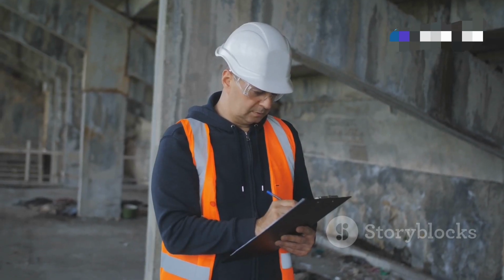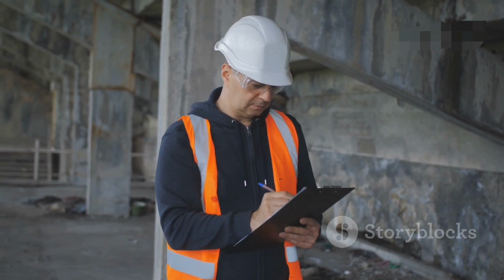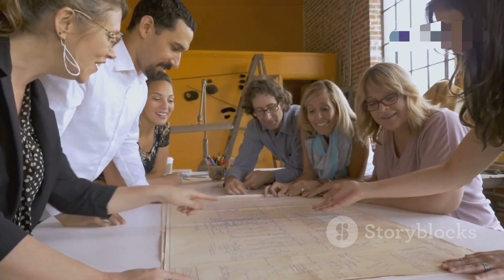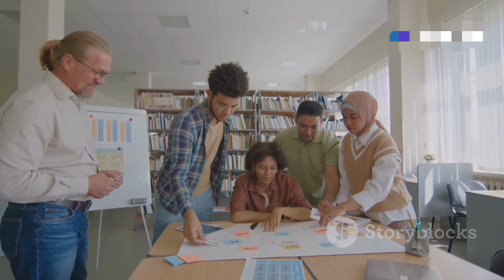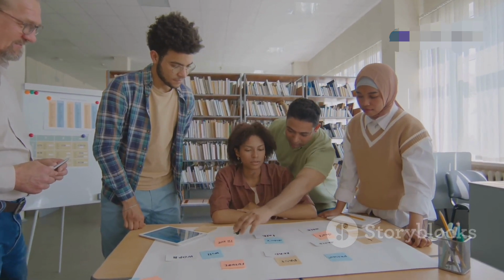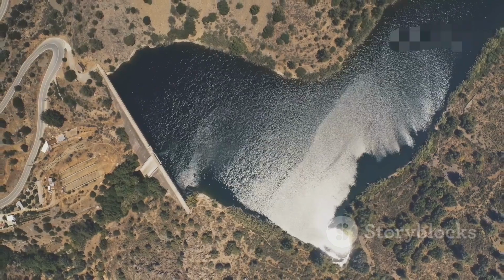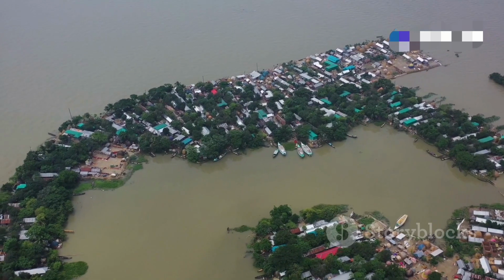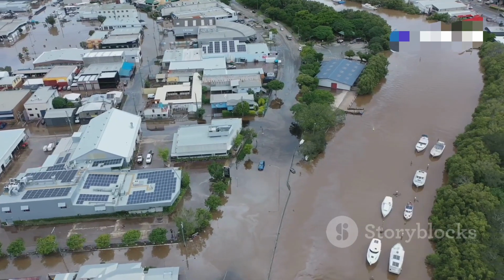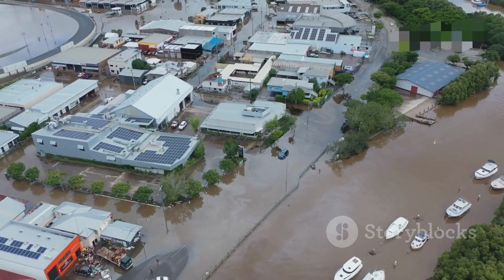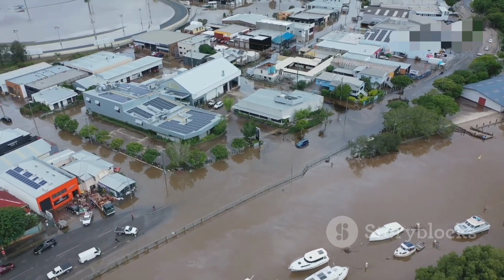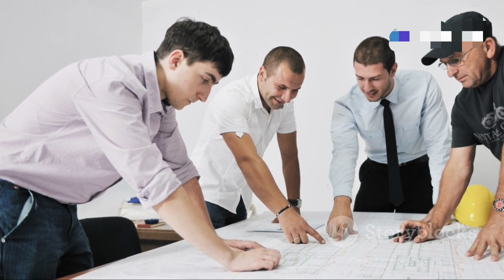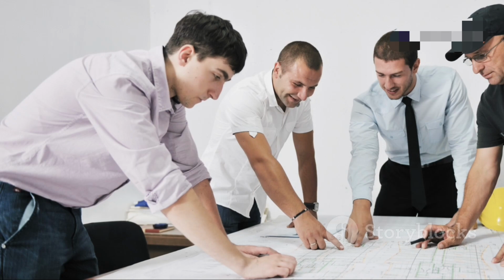The accuracy of these parameters directly translates into the reliability of the entire dam break study, which underpins crucial safety decisions. Accurate breach parameters lead to more dependable flood inundation maps and risk assessments. These maps are vital tools for community planning and for understanding who and what is at risk. If the breach is modeled as too small or too slow to form, the predicted flood extent might be underestimated. This could leave vulnerable populations unaware of the true danger. Conversely, overly conservative parameters might exaggerate the flood, leading to unnecessary alarm or resource allocation. The goal is to achieve a realistic representation of a plausible failure event, allowing for informed risk management and mitigation strategies based on solid technical analysis.